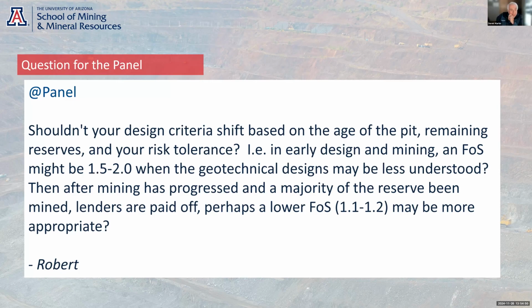Well, I mean, you bring up a good point in that you may be better off keeping your low factors of safety and degrading the rock strength to something that could represent the deposit. Because typically, certain classes of deposit have similar modes of failure, alteration products, and so forth. And bringing that into the equation, which is basically the geological model, and keeping the factor of safety in a range that we're typically used to dealing with, and then dialing down the strengths to reflect what we know about the deposit and the geology might be the better approach.